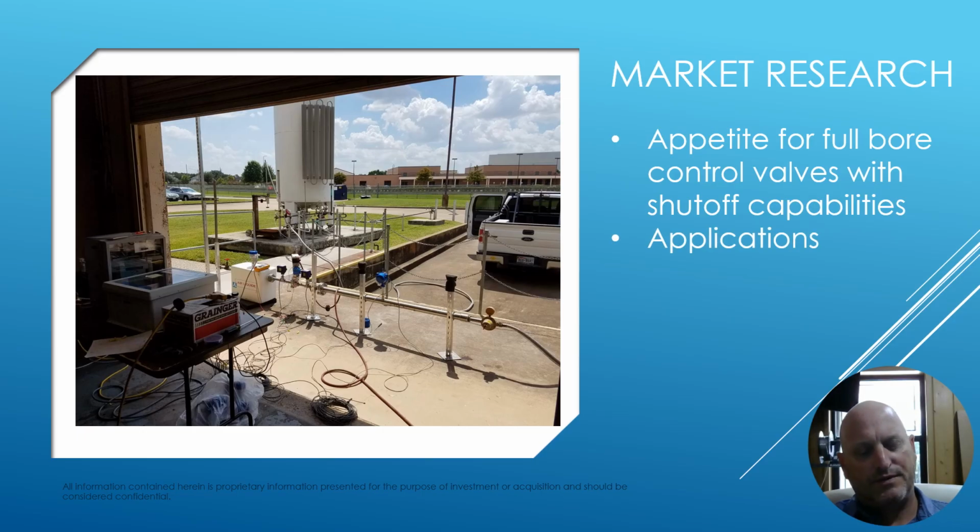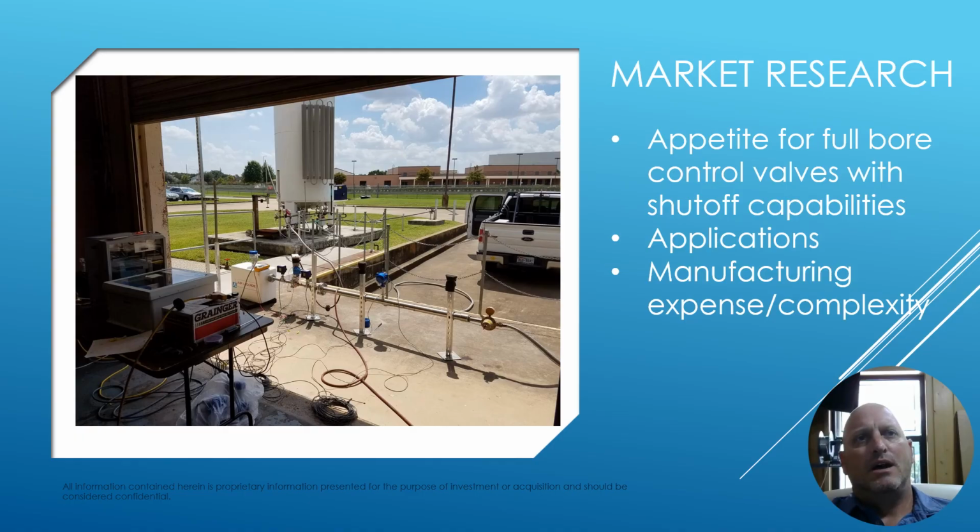For a full bore control valve, I'm thinking of steam control, fluid and gas control, fuel control, temperature loops, just about anything that you would typically use a globe valve for. That's what I want to go for. And anywhere you would specify a characterized ball valve, I think I've got a new technology that's going to be better than that.